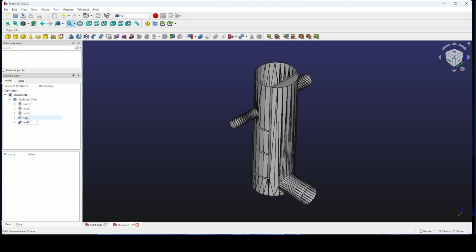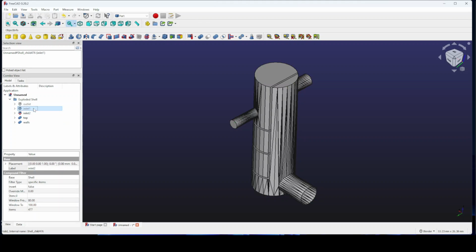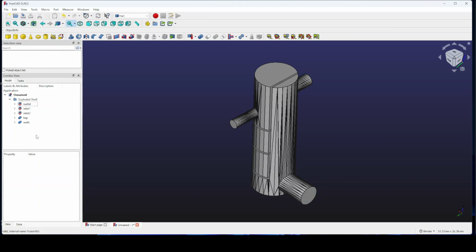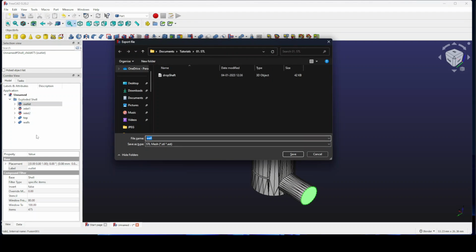Right now I can again display these things, and I can one by one now export these surfaces and use them for snappyHexMesh, which will be a part of another tutorial, and I will show you how to do that. So I'm just going to export these things and put them in a folder. Make sure you are exporting them as .stl files and name them for whatever boundary names you have.